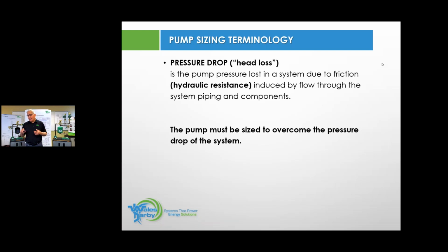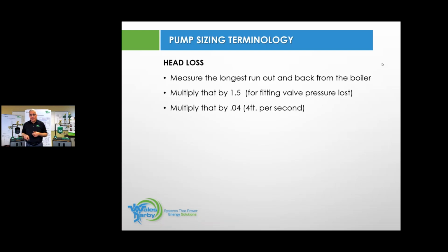We gave you an easy, simple formula, but always be aware that this gets you into the ballpark. It's not an exact science. We have the potential here, by using this formula, to oversize by maybe 50%, but it'll get you in the ball game, especially when you're on a job that's already been installed and you're doing service work. So when we're looking at a one pump zone valve system, we want to measure the longest run. If I've got 3 zones, 4 zones, one of the zones will be the longest. I want to focus on that zone.